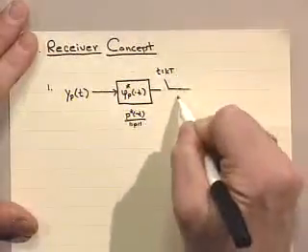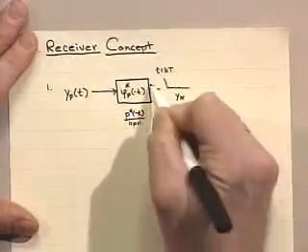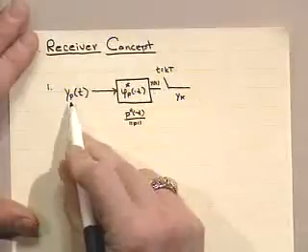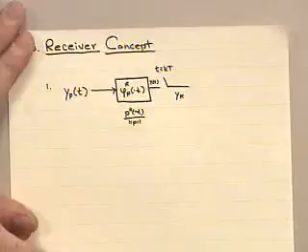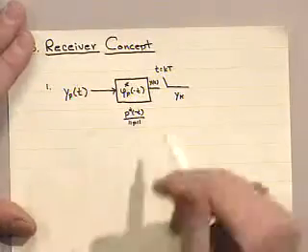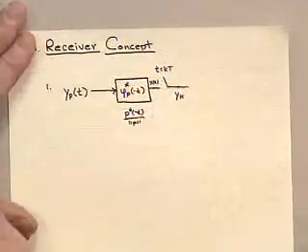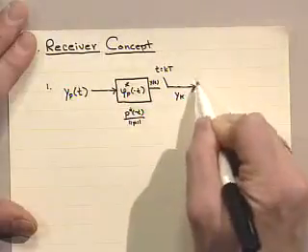And we proceed to call that y of k, and this will be y of t right here. So the reason I put a p earlier was because I knew I was going to presume I'm running through some kind of match filter. We know match filters are good. They maximize signal-to-noise ratio in some sense. So I have that maximized signal-to-noise ratio signal here run through a sampling device, call that y sub k, and at this point